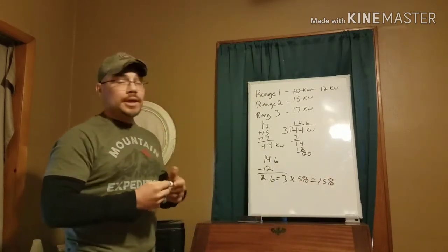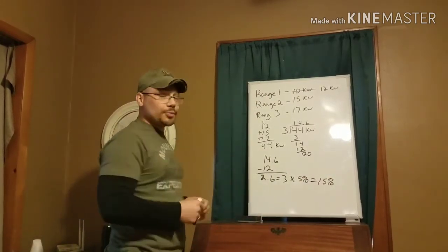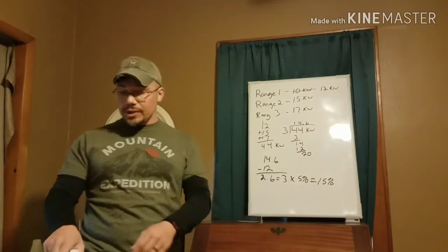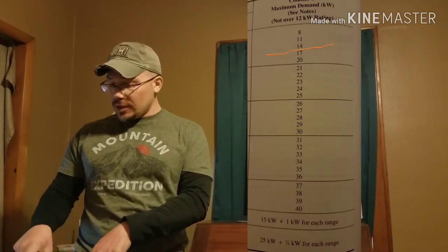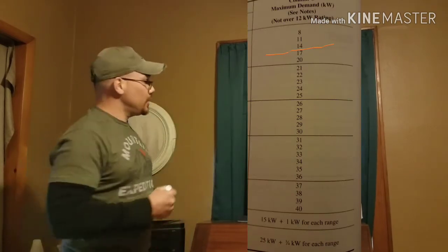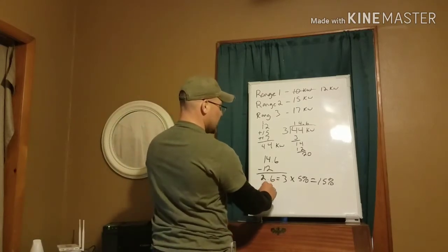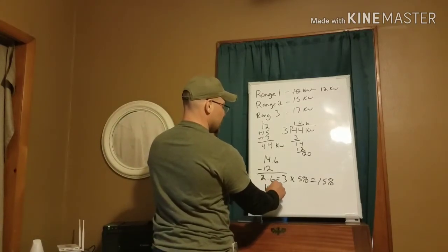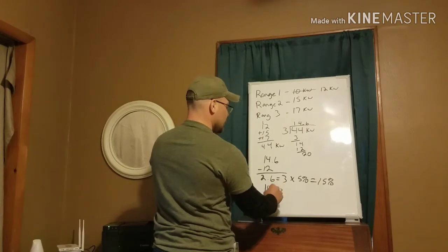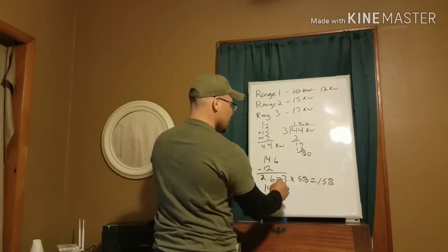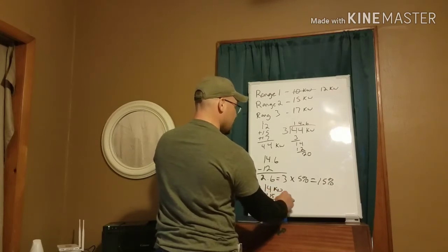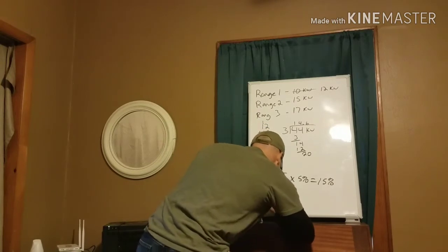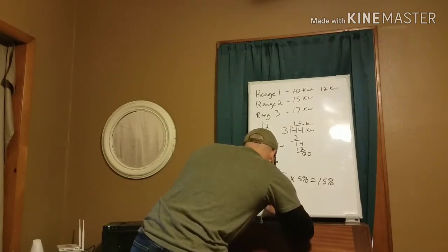Now again, this has worked out to be a lot like the last problem. We're using 3 ranges on table 220.55, number of appliances, 3. Follow that across to column C. It's 14 kilowatt again. So 14 kilowatt times the 1.15 equals 16,100.